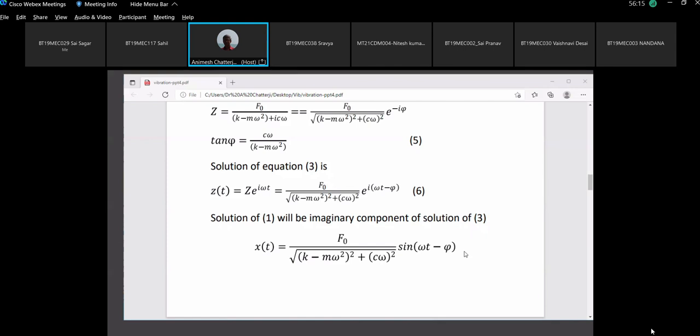If a vibration remains, I don't know, has third year Machine Design 2 started? Machine Design 2? Nobody is answering. Yes, sir. Started. So in Machine Design 2 you will be taught, I don't know who is teaching these days, the design of anti-friction bearings. Now, anti-friction bearings are designed against fatigue loading. And generally, the life of anti-friction bearings is taken to be 10 to the power 7 cycles. So vibration generally leads to fatigue failure.